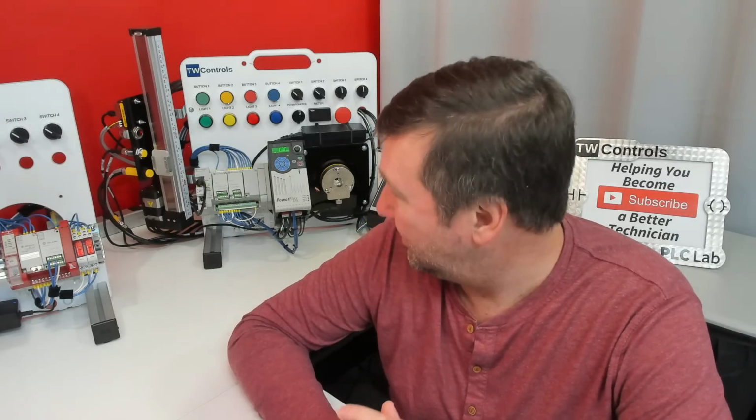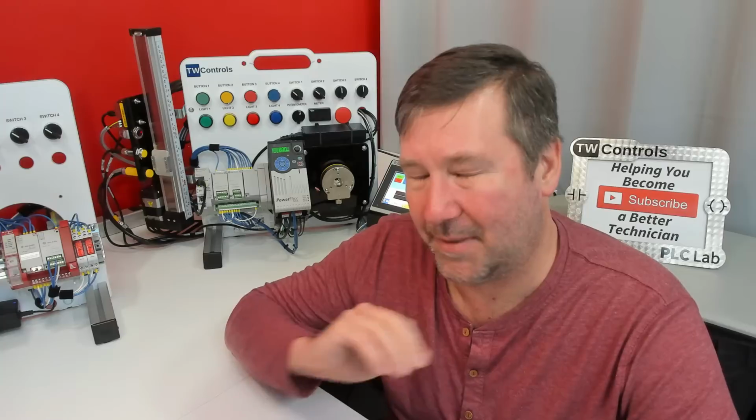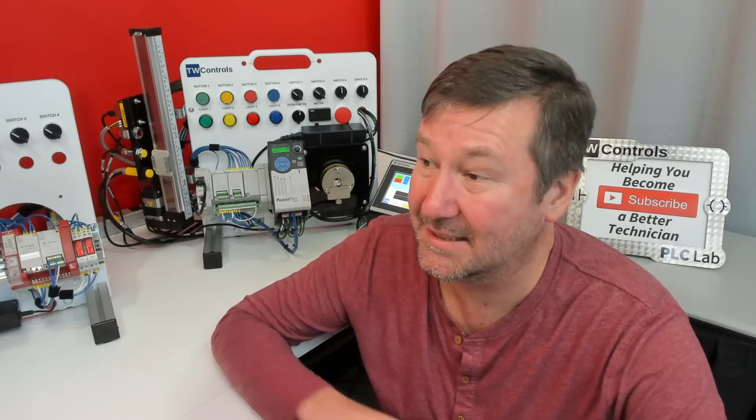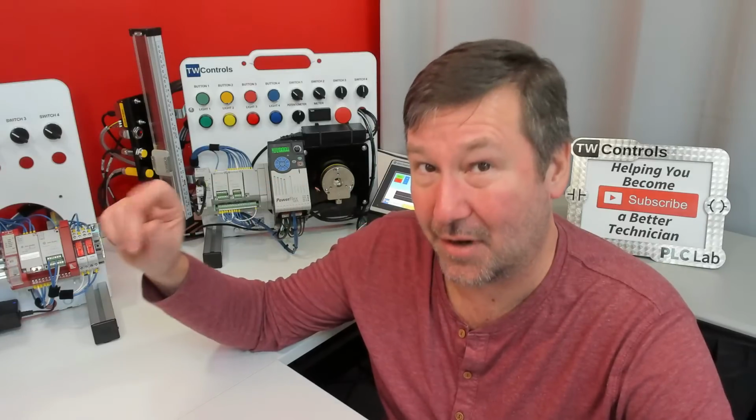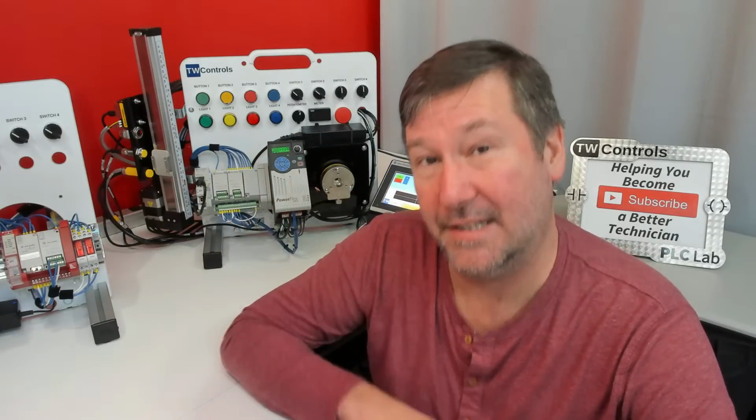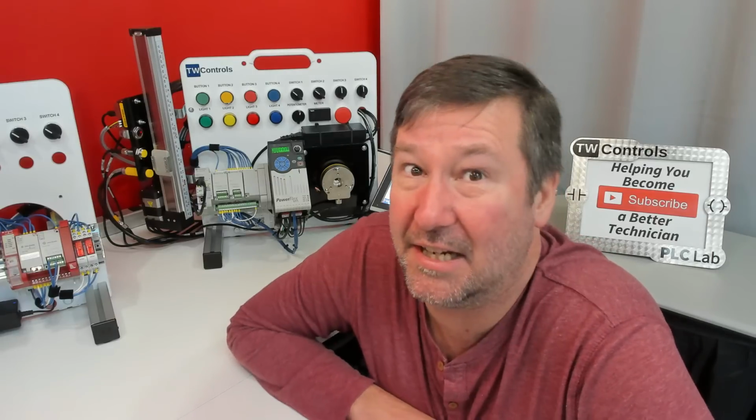I can take a PLC and arguably wire it and write the logic much quicker than I can make relay logic. And again, going back to the troubleshooting piece, this is the part that everybody building control systems misses: I can troubleshoot a PLC-controlled system immensely faster than a relay-logic-based system.